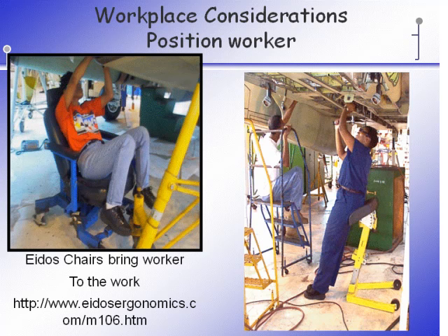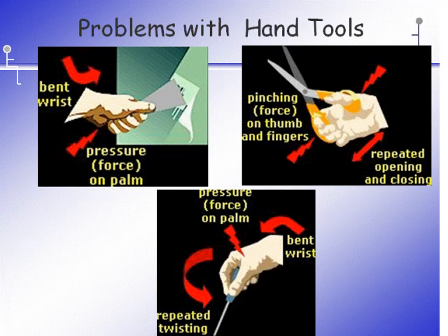So there definitely is some other workplace considerations for worker positioning. Remember how important posture is to the overall working environment, and we can change somebody's posture by raising or lowering the worker, by raising or lowering the work surface, or by raising or lowering the work piece, whatever it is that the workers are working on. So some way to orient that work towards the worker so we don't have to bend our bodies to reach the piece or part that we're working on.